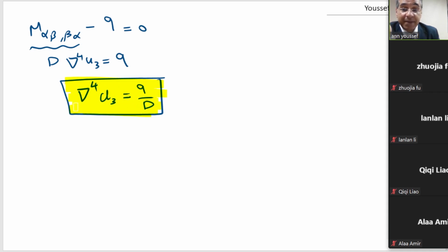At the beginning of the 20th century, this equation was very easy and you could solve it directly. Still, I didn't talk about the generalized Navier equation, which is the equilibrium equation in terms of the generalized displacement, because we have deflection and rotation now. We need to set it up in front of us in order to be able to form the fundamental solution, or get the kernels of the fundamental solution.